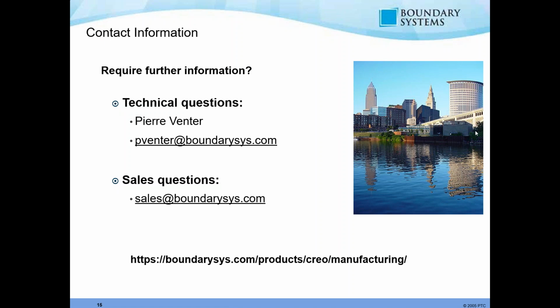Another question: does the setting to run on regen cause excessive lag? So will it slow down your machine? No, not really. You will notice in very large assemblies there's a little bit of a lag, but I would say anything below, let's call it, 200 components shouldn't be a problem. You won't even notice that. That being said, it depends on the parts and the checks and things like that. But I've done it now in a very basic assembly and it was instant. So it is fairly quick.